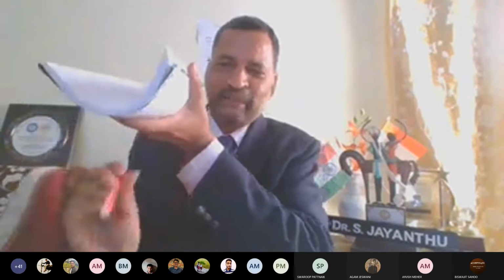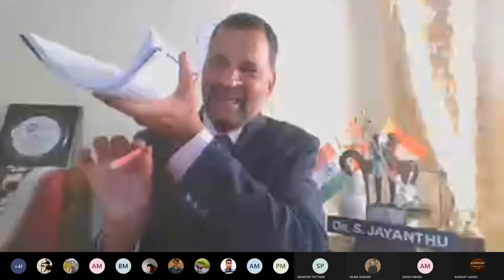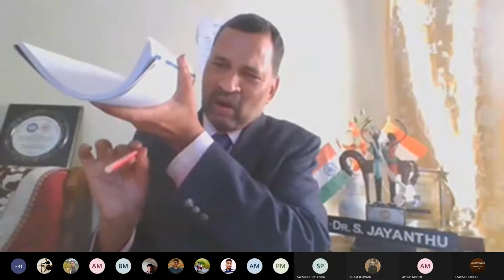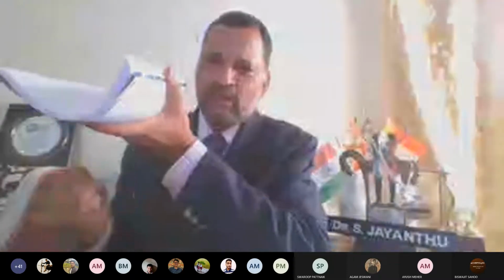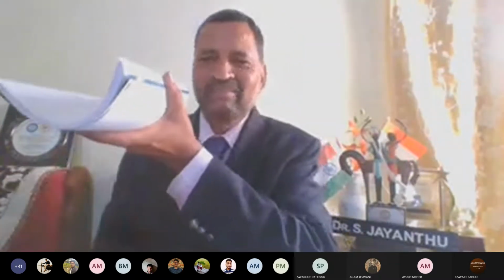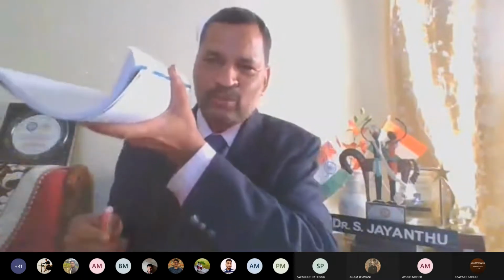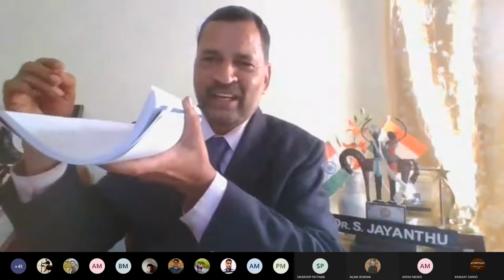Okay. Very simple to understand: when there is a 4 meter width of gallery, even the immediate roof rock, being so weak, may cave up to some height so that the total 4 meters gets filled. That is the capability, and that is bulking. Note these names down whenever I mention them.